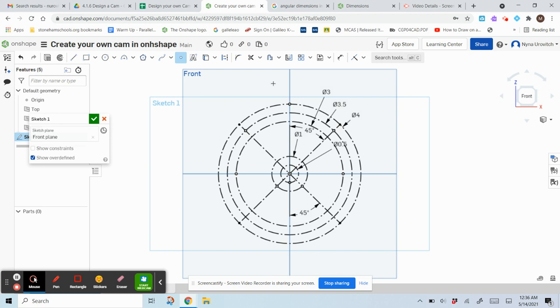Great. So I have all my points selected. I'm going to deselect the points, and now I'm going to move to the spline. The spline is better. It will make it less bumpy, but you could also use a straight line. I'm now going to connect my dots.